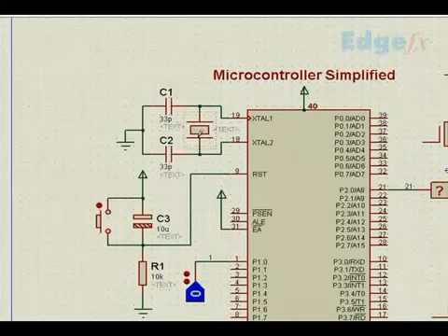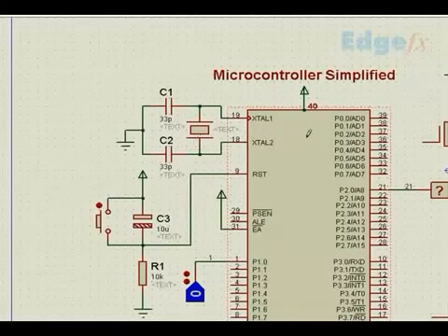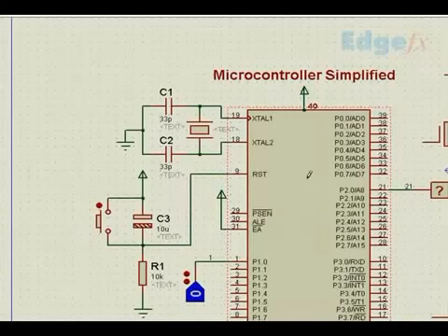So why do we need a crystal? It is not a crystal oscillator. It is just a crystal. The oscillation takes place inside the microcontroller. This gives an oscillation frequency. Many times the controller requires a certain timing reference. What is timing? Some programs require timing, and even the entire operation inside the controller requires timing operations. Since t is equal to 1 by f, or f is equal to 1 by t, unless I give a frequency reference, I cannot derive a time reference. And that is how the time reference comes for internal use and for many more uses.